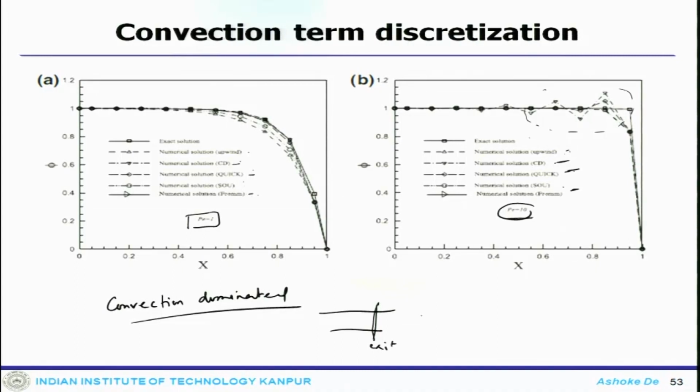However, the second order upwind scheme is expected to give rise to some oscillation in the presence of high gradient in the domain, if you have a shock wave or the like. So, that gives you an idea of some sort of comparison of this.